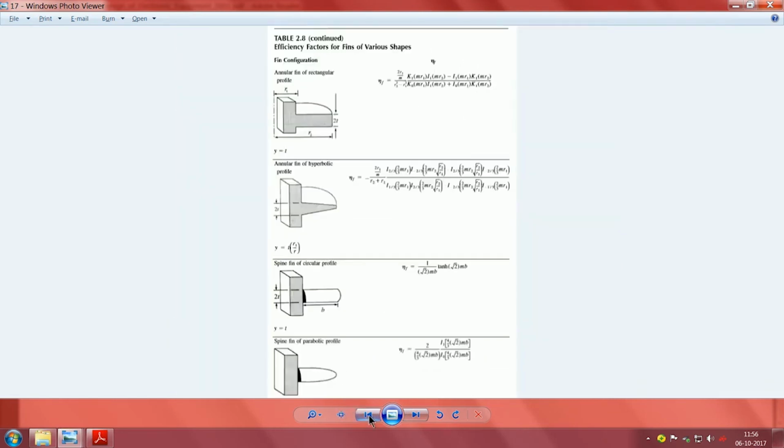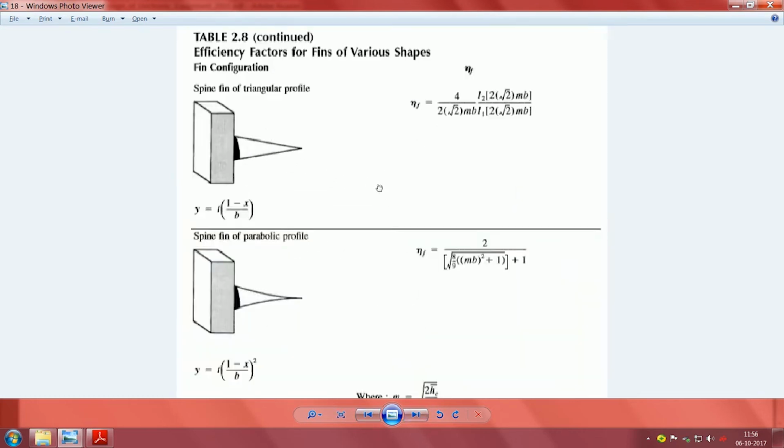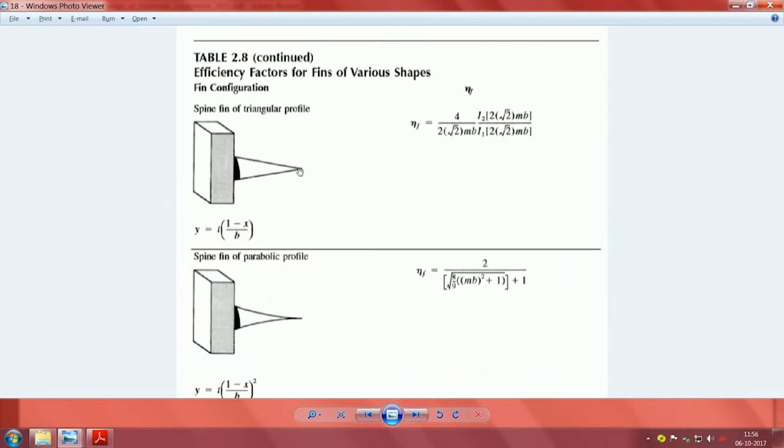The difference is that earlier they were all, as you have seen, annular fins, meaning the heat flow goes radially, and this is typically what you are likely to find as pin fin heat sinks. But because of manufacturing difficulty, usually they continue to be straight fins, plus they have a fan on top of it. So, go and check out a fan with a Pentium cooler.